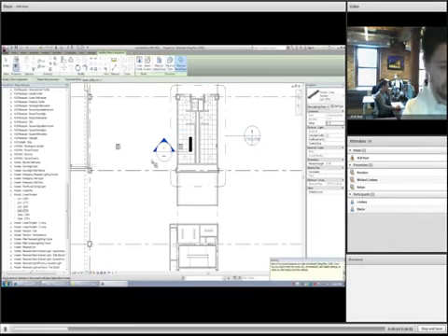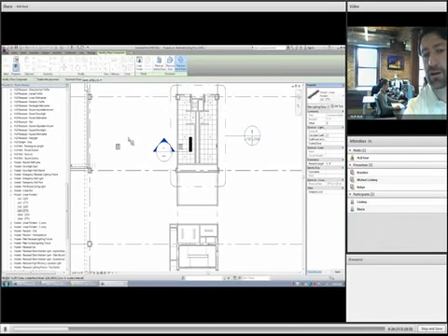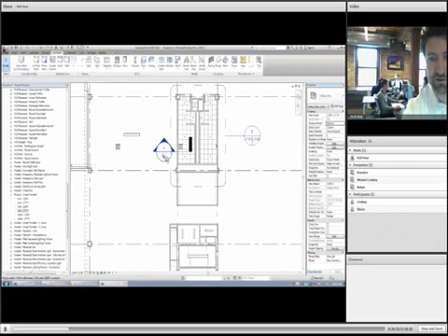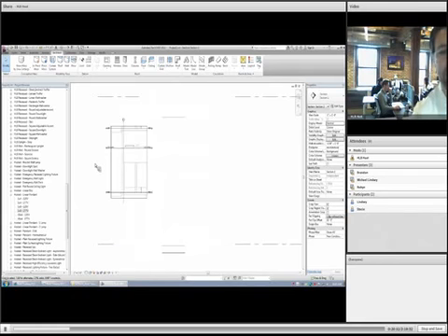Now, it says that it wasn't visible in that view. I need to go and check my properties before placing that fixture. Part of the problem was that I had it 8 feet above the floor, which doesn't work. So always, if you get an error that says you're not seeing this view, likely it's because the properties when you're creating that light fixture are out of range. You just need to go back. That was the offset? That was the offset, correct.